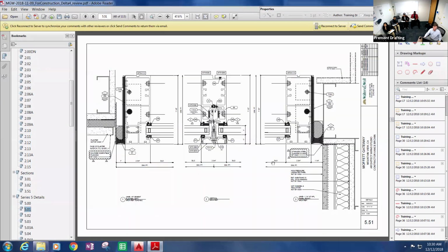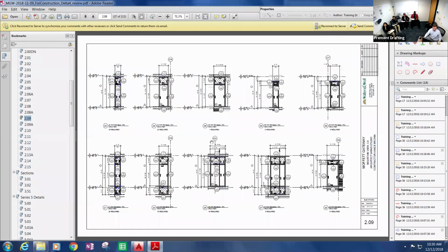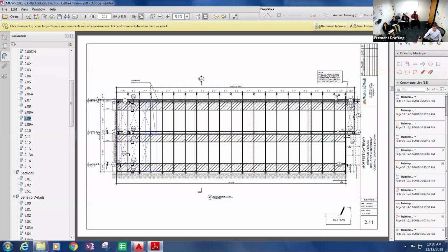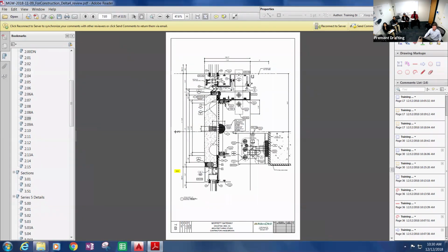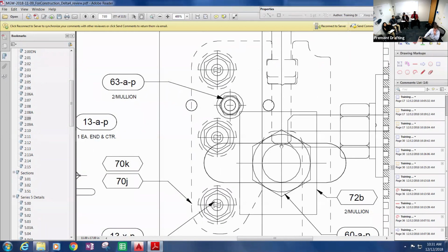I think there's some curtainwall on this show somewhere. Oh, there you go. Wrong direction. So it's this screw right here. By having it, that's your indicator, that's a dead load anchor. When it's removed, like that first detail, that's the wind load. So that's your visual cue in the details.